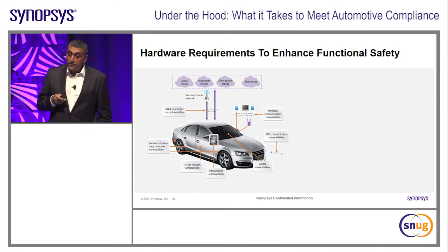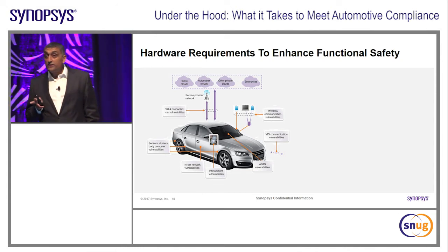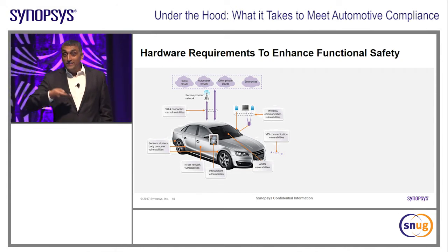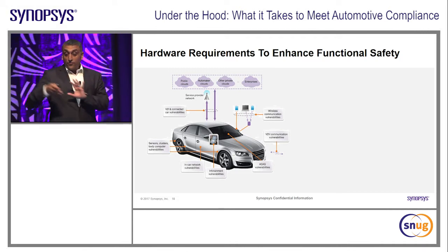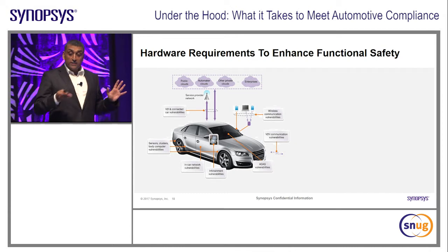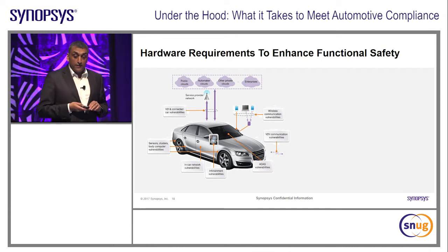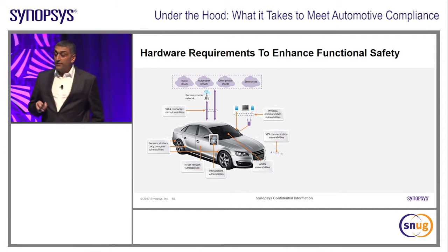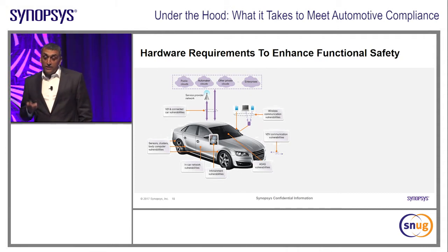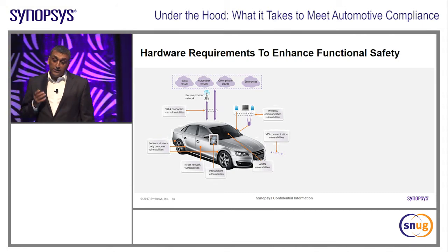One point here also is to understand the test benches. Remember, we're doing IP design, we're doing development, right? So you've got to build test benches once you build the IP, right? So for digital IP, you have controller test benches, right, for the RTL. Those test benches need to have some kind of identification. That identification includes things like error injection. You have different verification techniques.